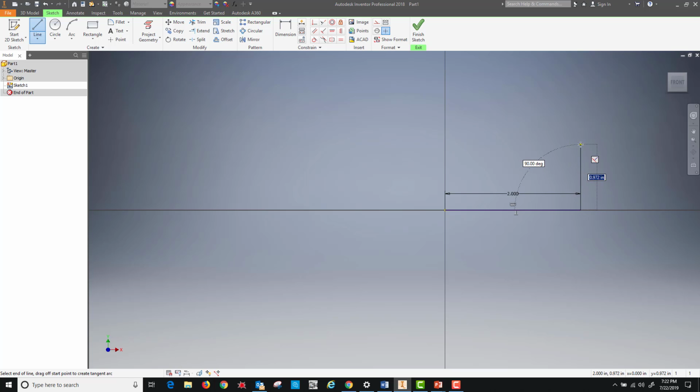We are still in the line tool, so we can bring this back up and it'll give us another option. If we look now, you're going to notice it shows us a size, and it also shows us the angle. So if we wanted to leave it at that size, we could leave it that size. We could say 0.5, we could tab over. Notice it gives an angle of 90 degrees. We're going to leave that 90 degrees. If we left click or hit enter, either one, they will actually allow us to make that line.